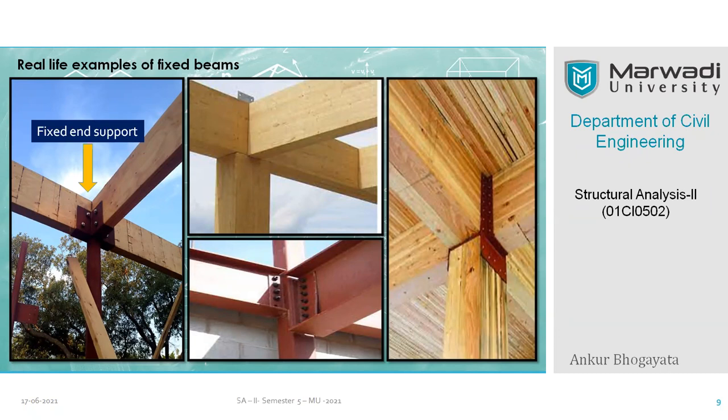Joists are thin members, usually supporting the floors and finally transferring the floor load to the girders. Girders are made out of timber only, but have large dimensions and can span more than the joists. So I selected this image just to show you that it is definitely possible to develop a rigid connection in any sort of material.